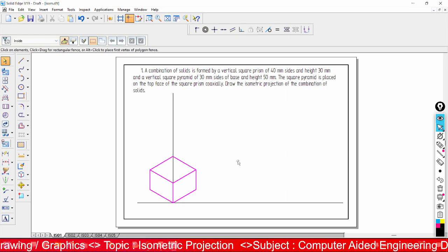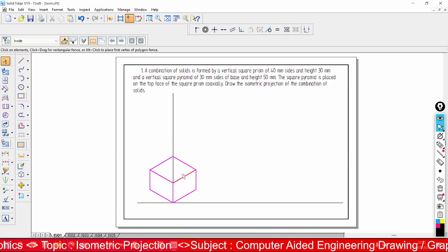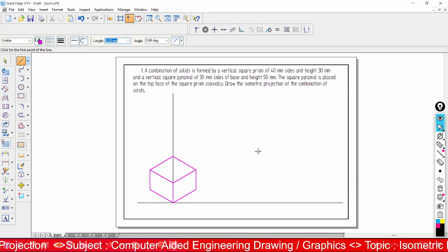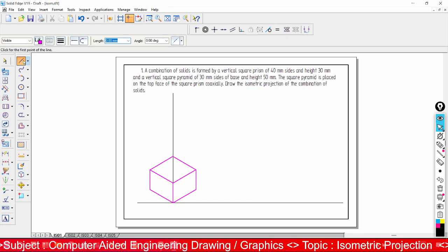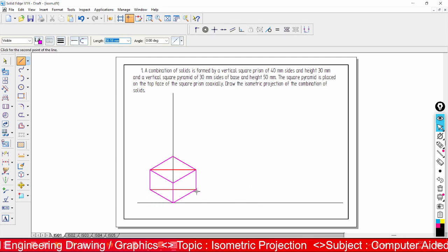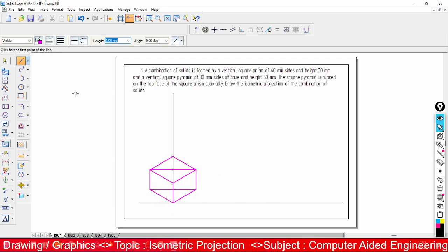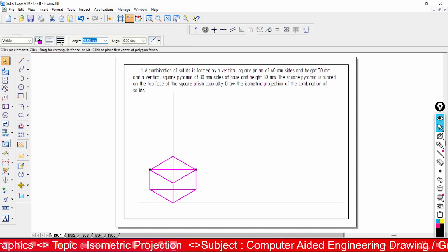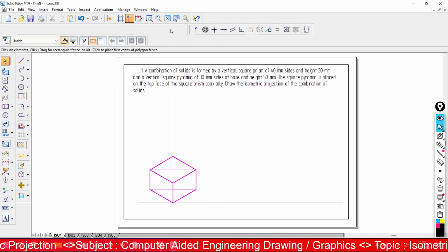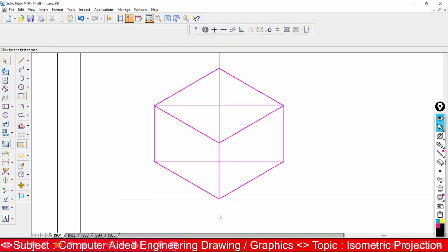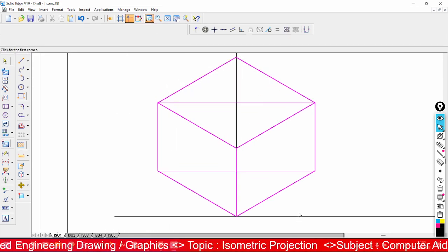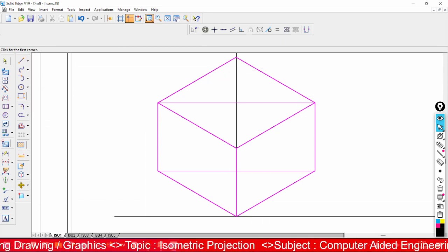Now as you need to construct an isometric pyramid, if you are perfect with the dimensions, you can start within here only, or else you can draw it outside. Now let us locate a center point here. Now this is to be 0.13. Now this also has to be 0.13. Just go for zoom area and check whether it is properly drawn or not. Some points are not connected to each other, so you must take care of the connection of every point.